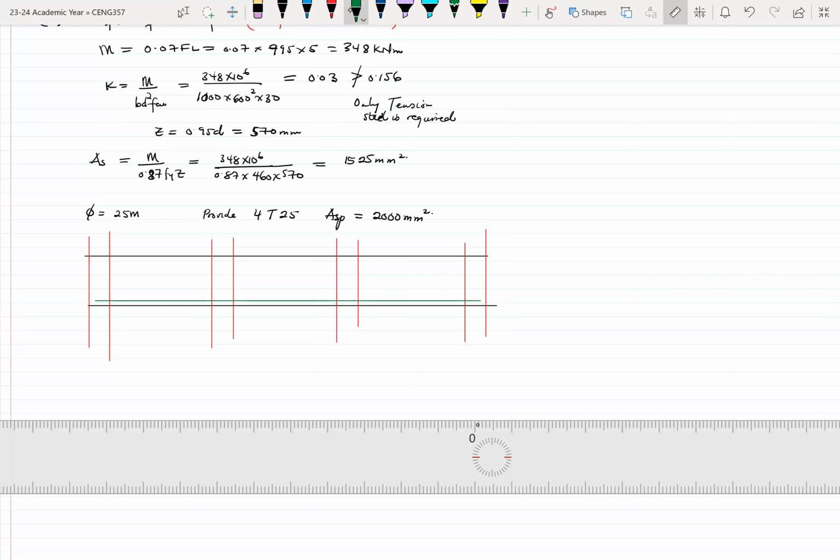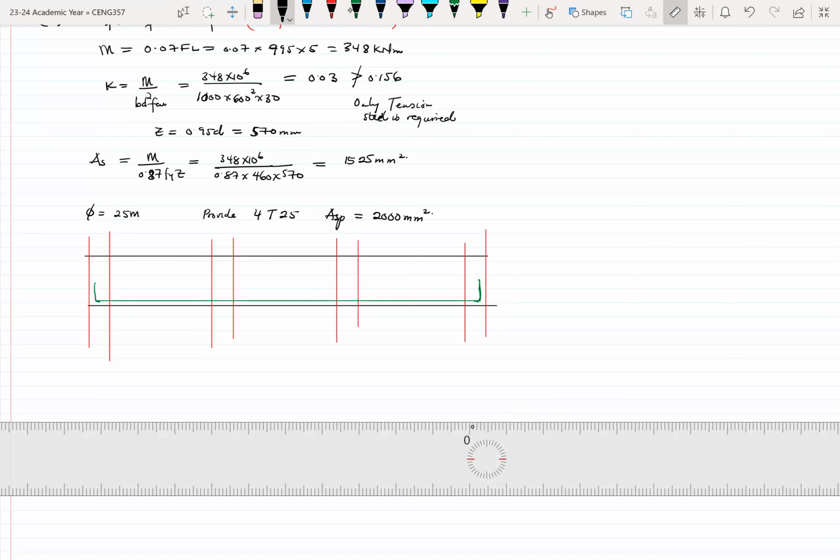All right. So you have your anchorage this way. Okay. So this beam here, this one here like this, is 4T25. All right. Definitely the length of the beam, which is 15 meters, is more than the length of the rebar on the market. Most rebars are about 12 meters. All right. So it means that at some points you may have to join the rebar. So you may do some bit of lapping somewhere here.